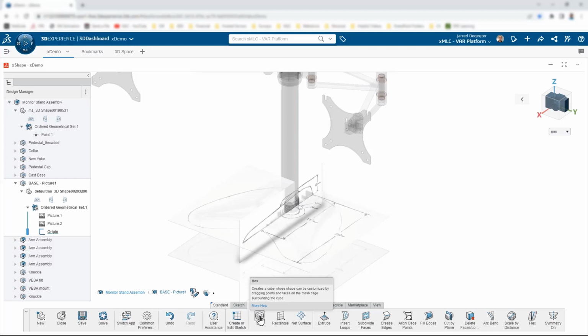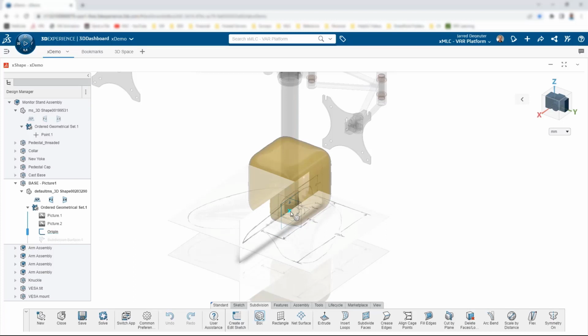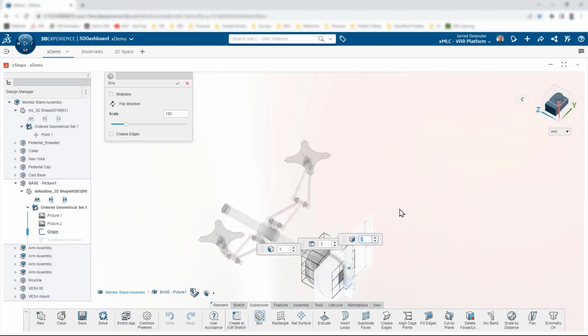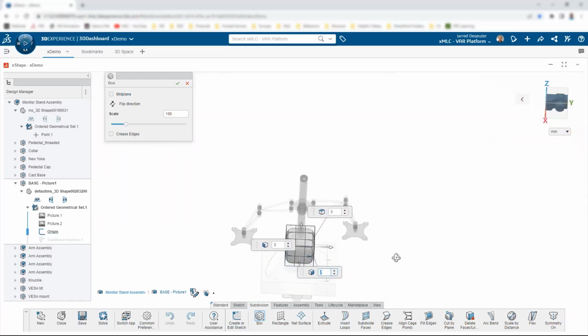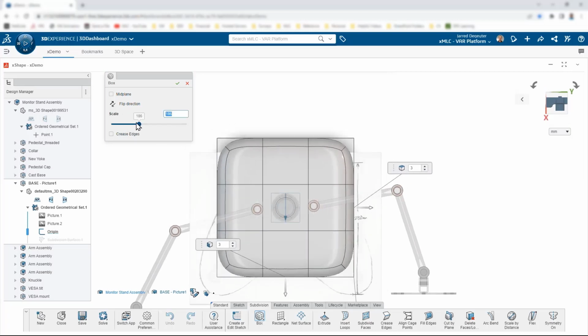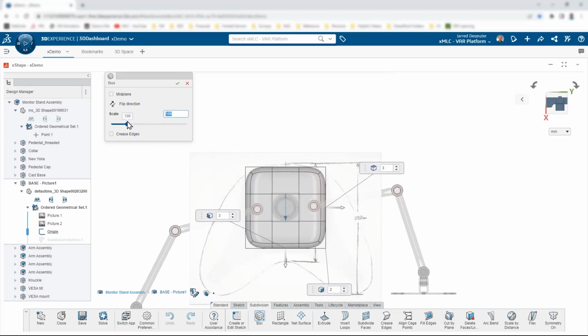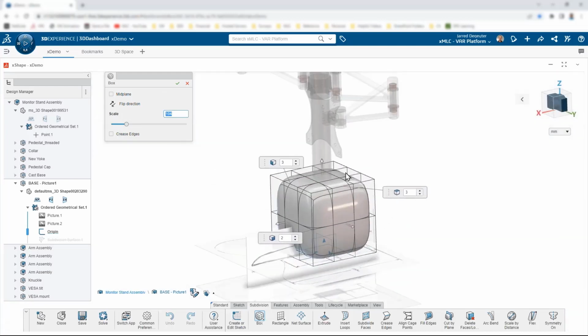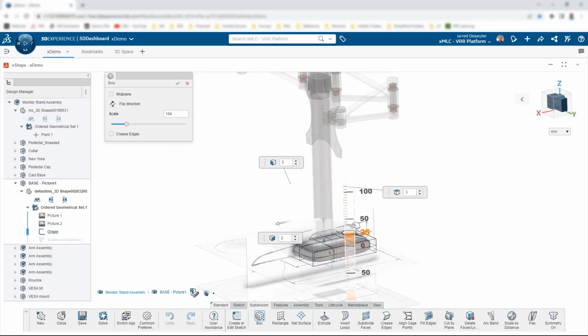But basically you start off with dropping in what we call a primitive, which is just a shape that's been subdivided already. So we can drop these in, and we can control how many subdivisions are actually present. We can rotate around here, and we can even scale this before we actually confirm the drop of this primitive shape. So we can scale this up or down, however large we want this to appear. So I'll pop it in somewhere maybe in that range right here. And we could probably shrink this down a little bit too, just by pushing and pulling on these arrows. So this happens pretty smoothly.